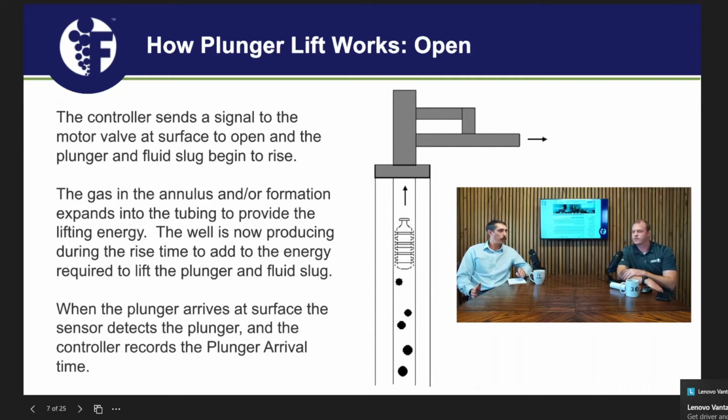And in a conventional plunger situation, that helps avoid loading the well up. Because if the plunger's not coming up, it's not bringing fluids up, and those fluids are just continuously stacking in the well. That makes sense. And then again, just like off time, we're going to talk about it from a time perspective, but there's other ways to control that too. Or is that one typically time? That one's almost always time.